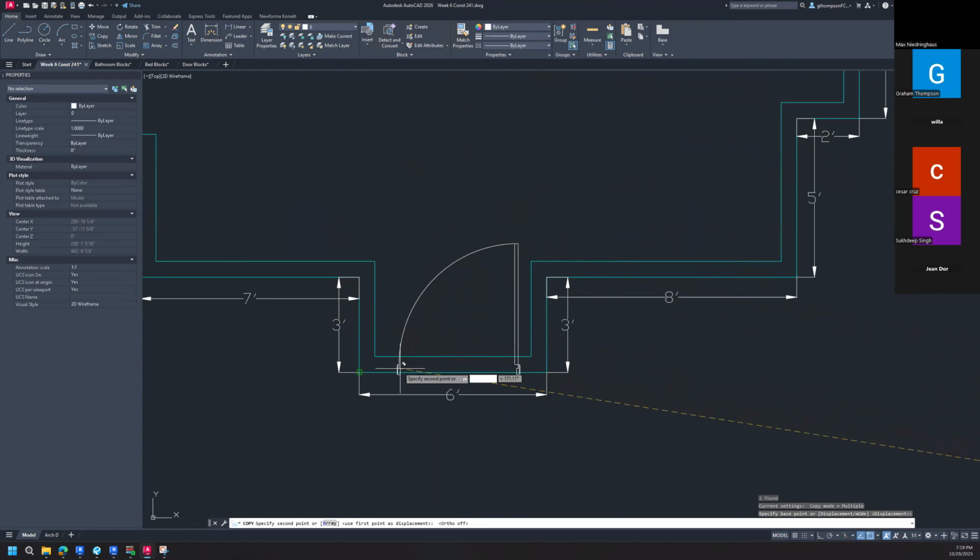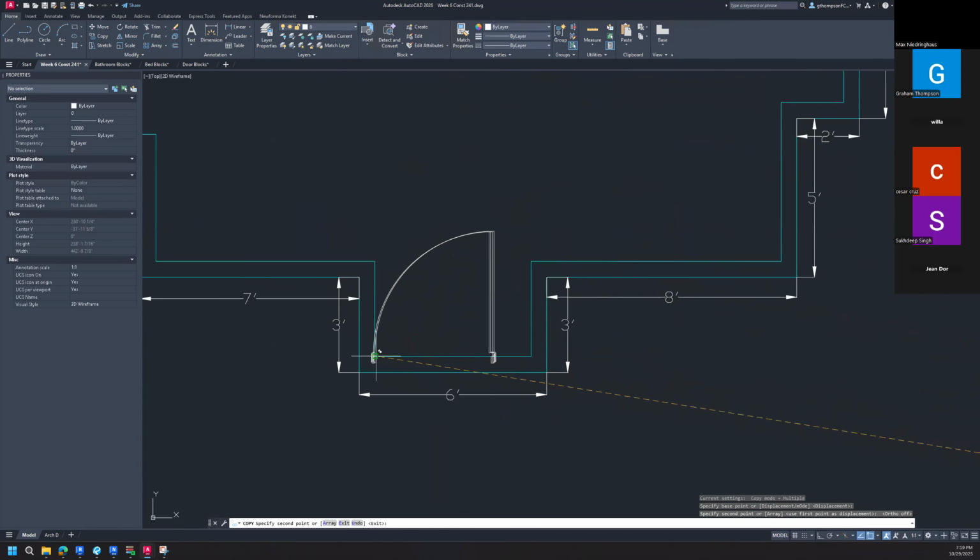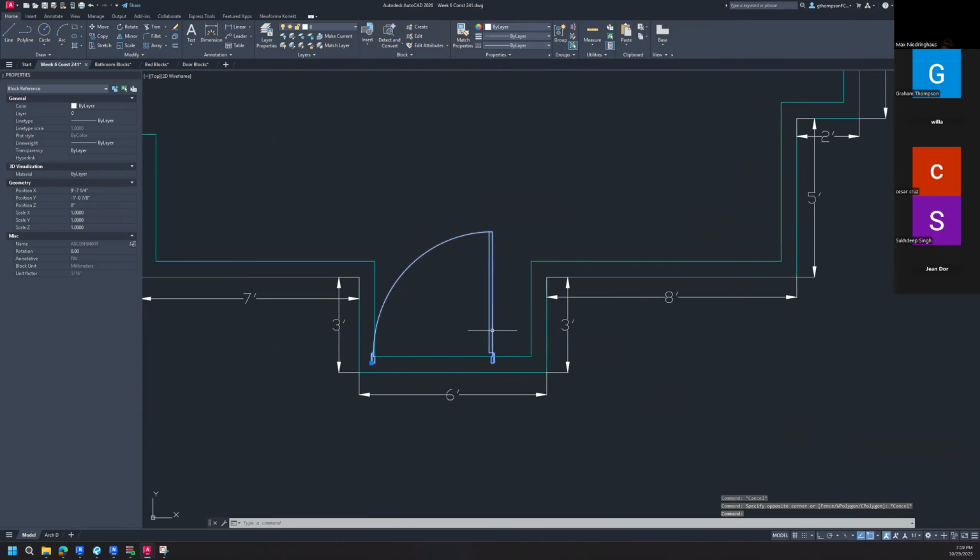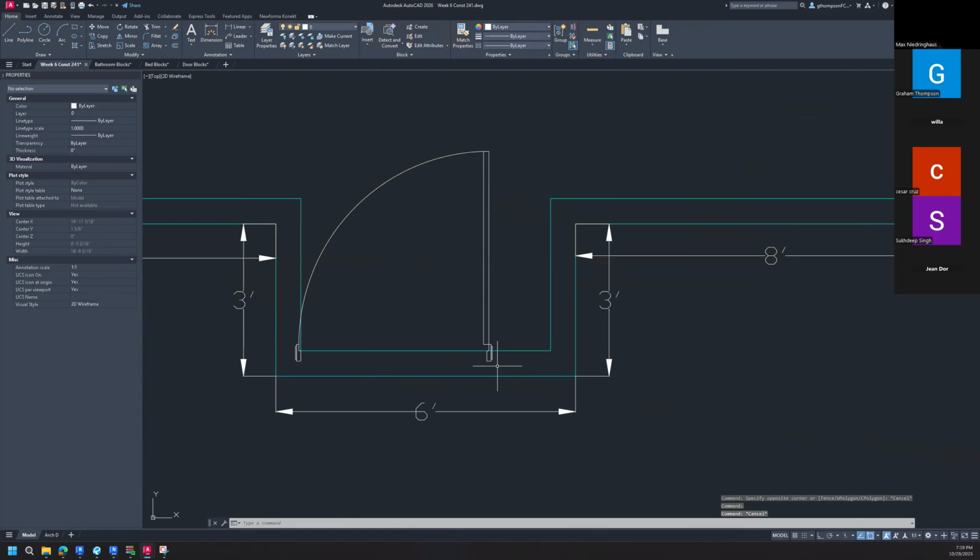Okay, it's a pretty big front door, but that's okay. That's why I built the opening the size I did. And so I just placed it on the corner. I'm going to go ahead and take a dimension real quick just so I understand where center is going to be on this. So use my dimension tool, and I like this guy, my line dimension. We're going from here to here. So that's 1 foot 14 inches, right? So I'm going to move this over 7 inches just to center it up.